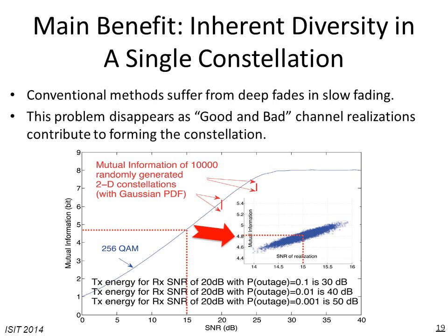For the case of 256 QAM, the energy is the transmit energy, which is also the receive energy. The 256 QAM is over an AWGN channel, and it is used with equal, uniform probability for its points. So you see we have a curve that, at an SNR of 0 dB, starts from 1 bit per 2 dimensions and saturates at 8 bits per 2 dimensions.